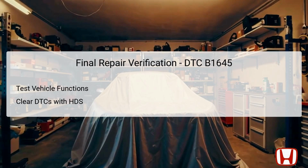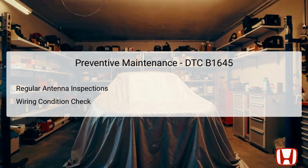A successful clear without the reoccurrence of DTC B1645 suggests that the repair was effective and the vehicle is back to optimal performance. It's crucial to monitor vehicle behavior for a few days post-repair to ensure no further issues arise. Performing regular preventive maintenance can significantly reduce the occurrence of DTC B1645 in Honda Accord vehicles. Regularly inspect the driver's door LF antenna and associated wiring for signs of wear, damage, or corrosion.